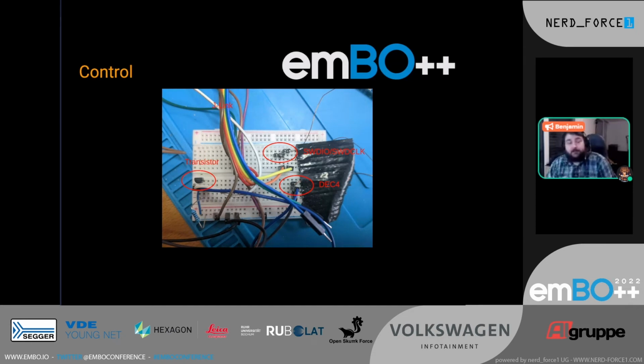One leg of the transistor is connected to ground. One leg is connected to the decoupling capacitor and decoupling pin 4, which also goes to the decoupling capacitor. And the third leg is connected to the GPIO output pin of the Bluepill board. So whenever the Bluepill board pulses the pin high, it causes the transistor to conduct, which will short the decoupling pin to ground.